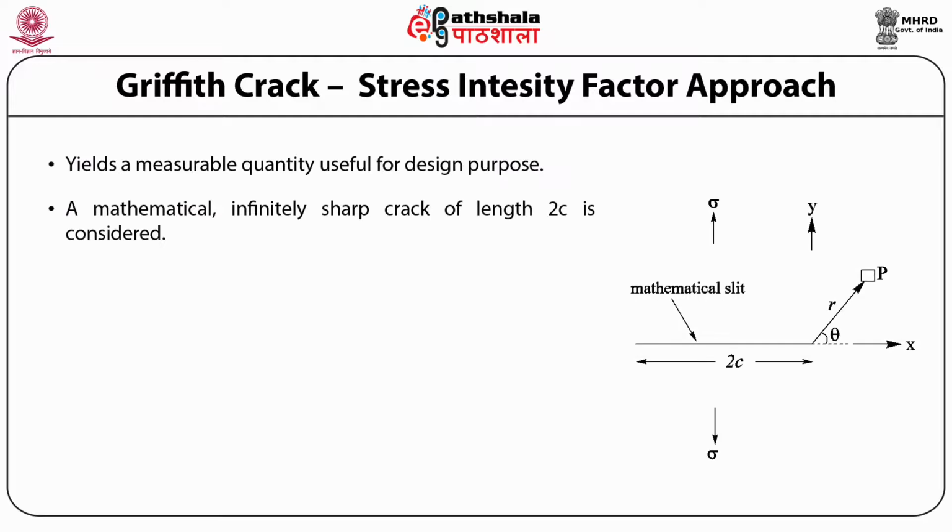Griffith crack, the stress intensity factor approach. This approach has turned out to be the most useful as it provides a directly measurable quantity which can be used for design purposes. In this approach, a mathematical infinitely sharp crack of length 2c is considered. The stresses near the tip of such a crack can be calculated by the elasticity theory.